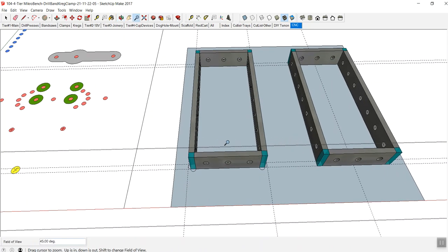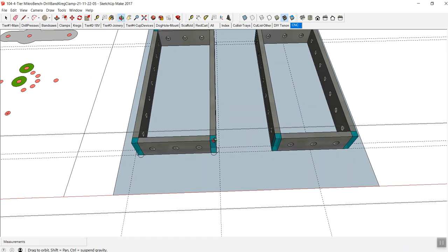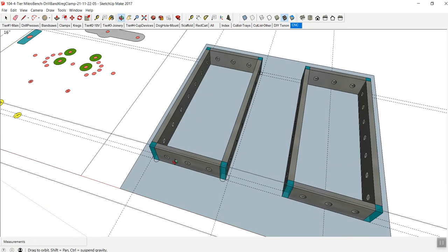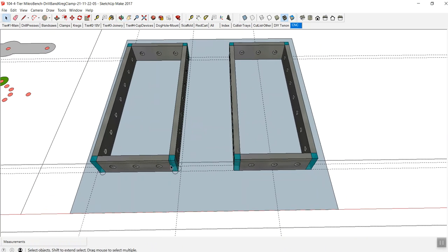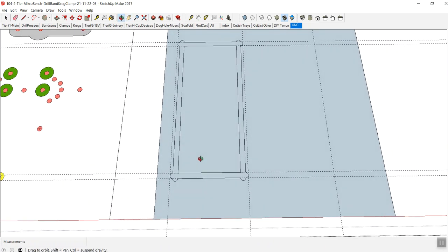flat bar, that I need to put into some sort of wood form to hold them just temporarily together. Even though it's wood and I'm welding, blah blah blah. I just need to hold them temporarily so I can do a little tack weld there at the corner. So that's basically what's going on, and I want to have some flexibility in those pieces going back and forth. So this is basically the design. I'm going to hide those, and this is the design that I figured is going to get me by.